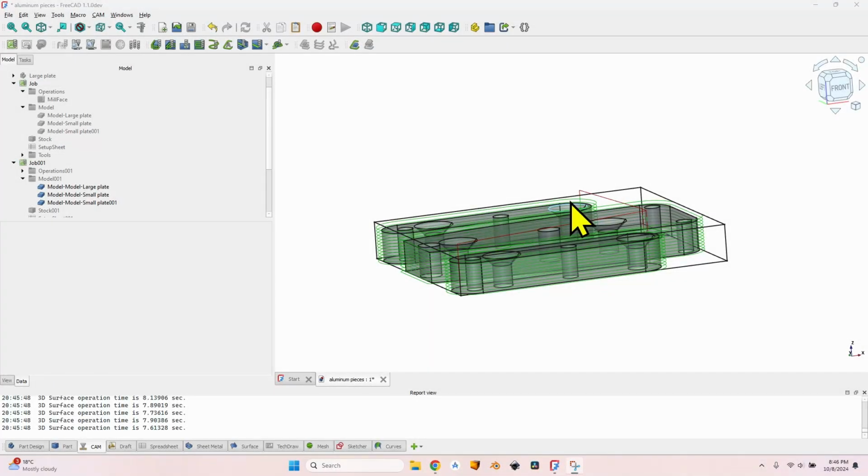So this is all. You have seen how I designed the pieces, how I created the toolpath, how I split the operations. As I've told you, when milling them, I have first flattened the piece so I get the correct dimension of the stock. Then I milled the holes because I took advantage of the fact that the pieces have holes in them. This way I was able to hold these small pieces to the table very easily. I have also shown you how to solve certain situations that maybe you didn't realize when first creating the toolpath. As I've shown you, I had to create some tags to hold the remaining pieces to the table to avoid them flying around. I hope this was useful.